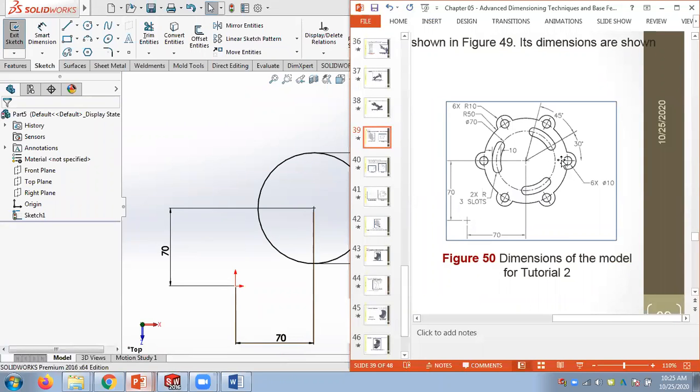Now if we have to draw these circles, I can draw only one circle and pattern this. So it's better not to start from these unknown places. This is horizontal, this is horizontal, so it's easy to start from this one or this one. So we will start by drawing two circles. You don't have to worry about the arc shape initially because we can trim that later.